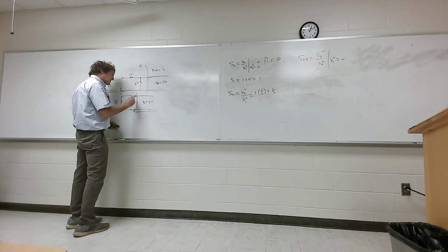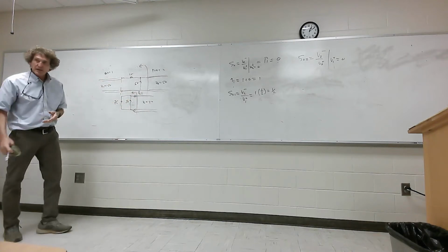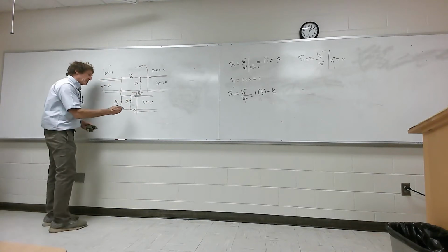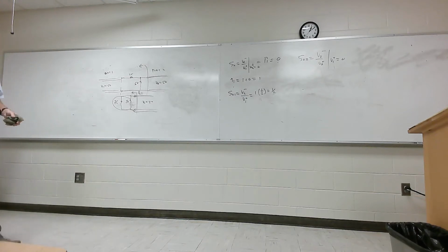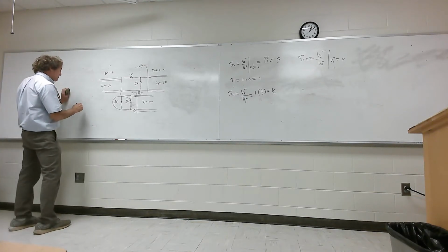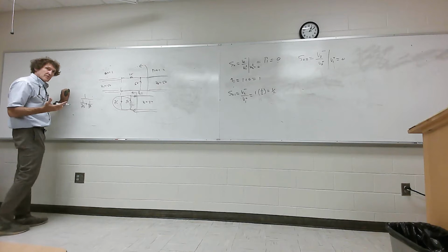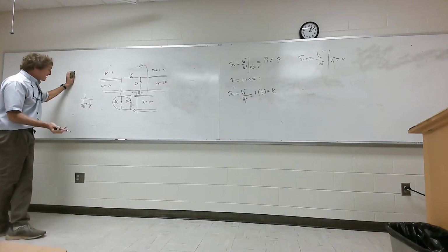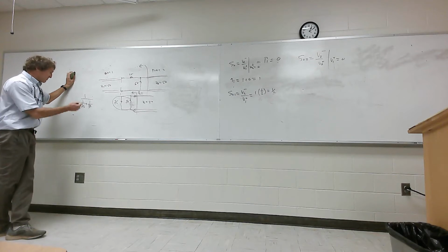So when I take a look at that equivalent and I want the reflection coefficient there at port 2, what is it? Well, I need to take the parallel combination of those two, don't I? So what is that? Well, it would be 1 over 1/75 plus 1/50 is a good way. That's the way I do it, and you can do it your own way. And what's that going to be? 30 ohms. And you can prove that to yourself.